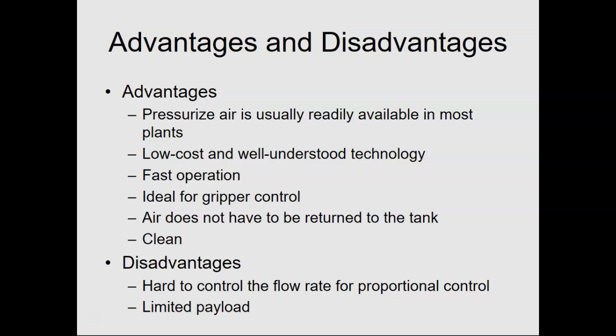Any time you're using something like hydraulics, and especially when you're looking at using specifically a pressure washer, PSI depends on the job you're going to do. With a lot of those, what you have to look out for is what tips come with it, because the tips actually are what allow you to do the cleaning with pressure washers. When I say tips, I mean they have different spray patterns, and those actually deal more with the pressure.